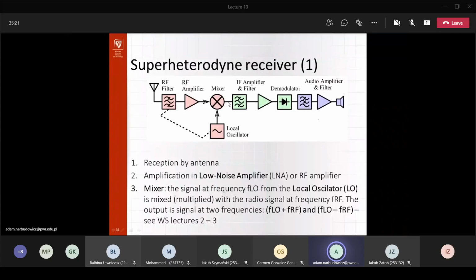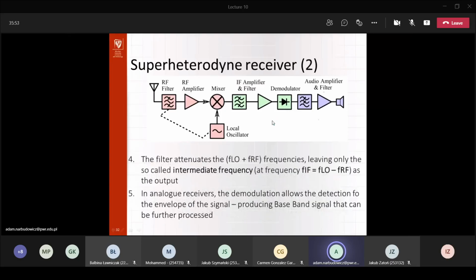One clarification: I may finish this block and then explain. Over here, we will again make a selective filter, predominantly to get rid of all the higher order modulation components. And we end up with what's called IF, which, we're here at step 4, stands for intermediate frequency, okay?